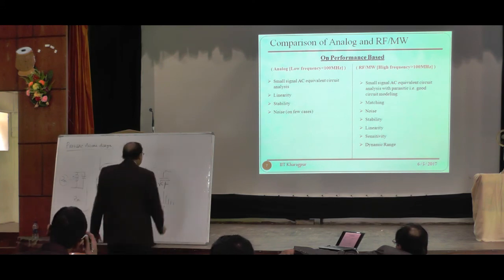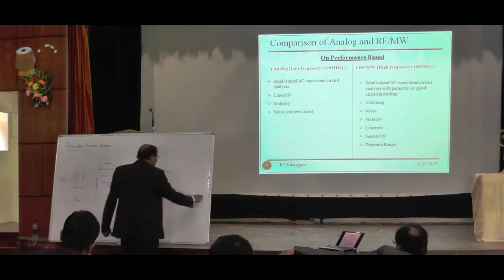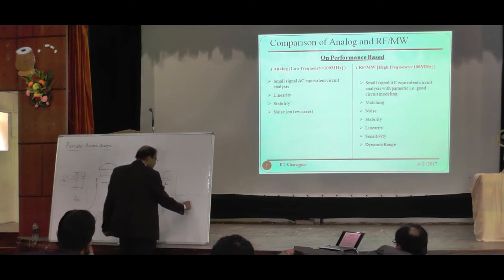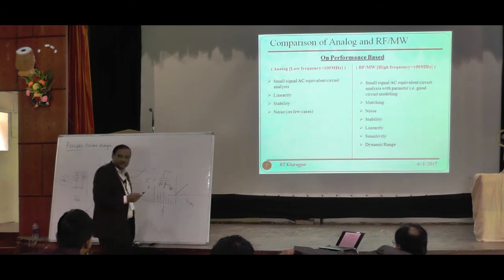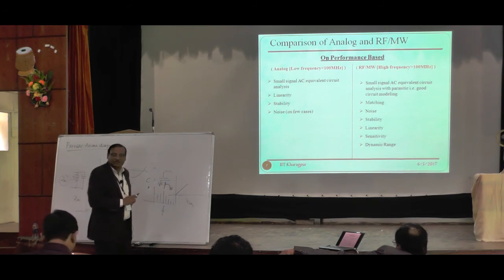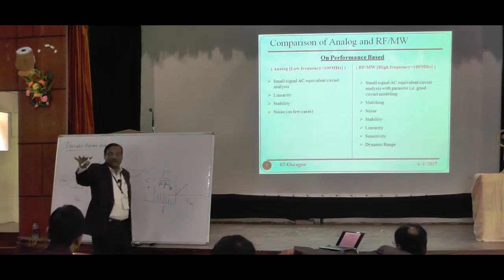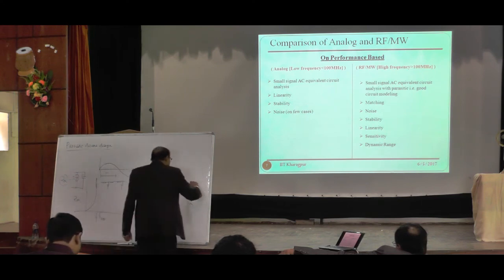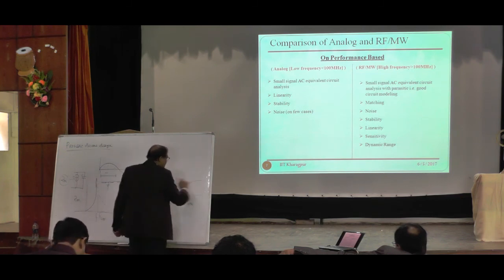So if you look at an amplifier, linearity and nonlinearity, what will happen? This is my input and this is my output. Initially in the linear region, I need some kind of a linear gain, right? After that, what will happen? Will it go lower or will it go up? Conservation of energy tells us the amplitude will lower down because the energy is now distributed across other harmonic components. So instead of continuing along the linear path, it will now drop.